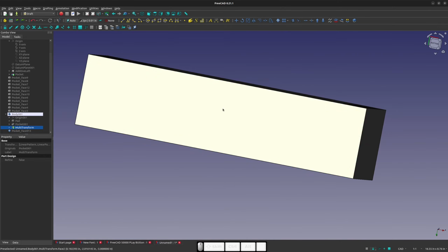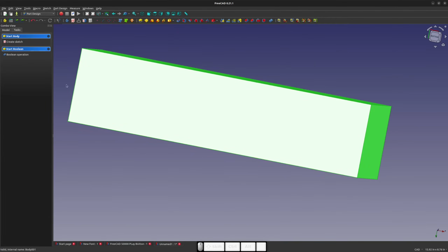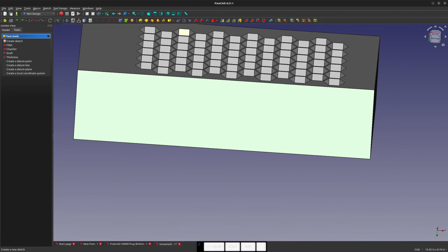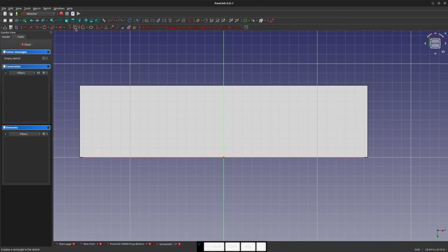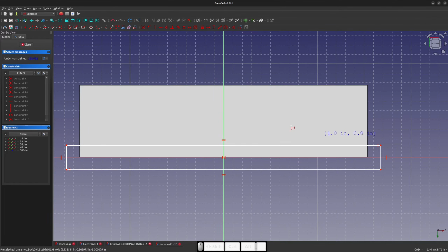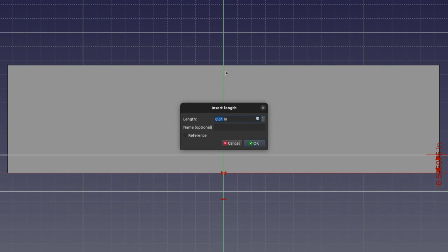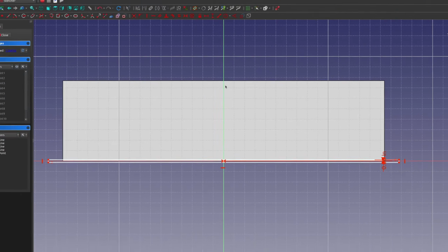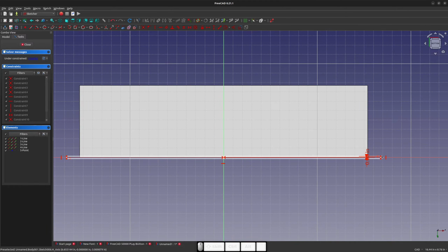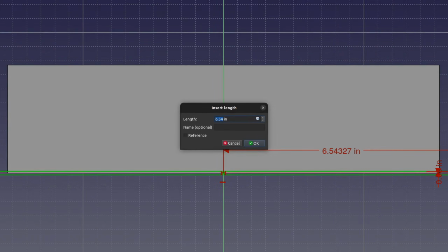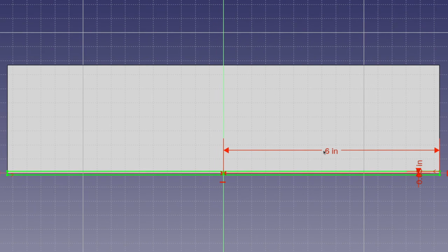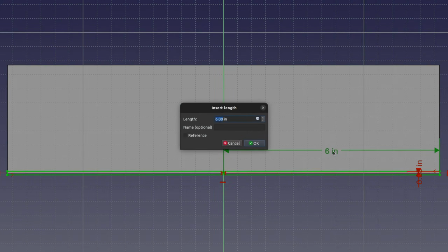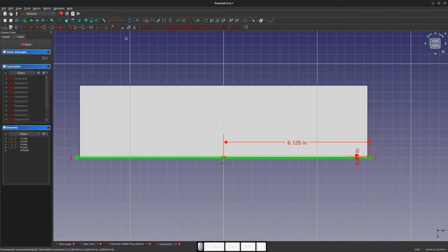But before I do, just to make sure I get a clean trim, I'm going to make sure that I'm on my active body 0, 0, 1. I select this face, create a sketch. And I don't think I have to be too brilliantly precise about it, but I'll create a center rectangle along here. We'll select this point and vertical dimension. We'll give this point 0.5 perhaps. Right. And then maybe same point horizontal. 6, maybe I'll go a bit bigger. 6.125, right? And then we'll close,